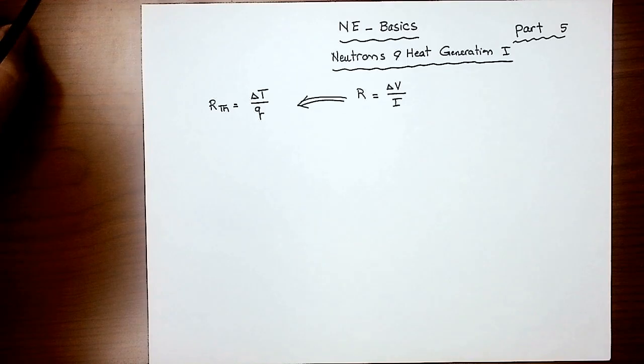And the only weakness or the missing information for the thermal circuit analysis approach is we were always assuming a steady state, which is going to be a continuously assumed boundary condition all the time. But we also assume there is no internal heat generation. And if you don't have heat generation, this means that you can simply use that thermal resistance principle. But with heat generation involved in the problem, the thermal resistance had to be modified a little bit.